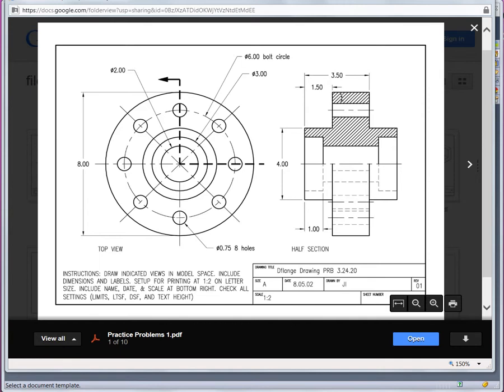Now, you can see that if we look at one half of this top sketch, it's symmetrical on the other side. Okay? So a couple things that we want to keep in mind include using the origin to orient our sketch lines to produce our model, and to use center lines for axes for mirroring some of these sketch lines. Okay, so what I'll do is I'll move this out of the way so we can lay out our model.